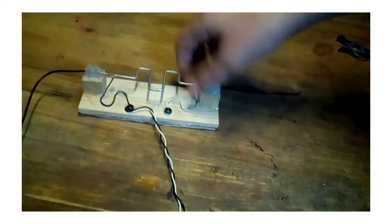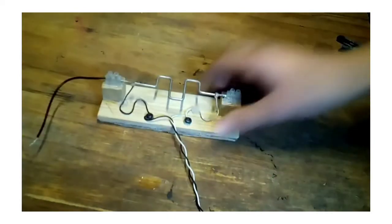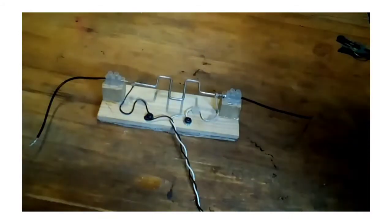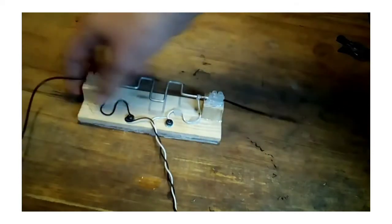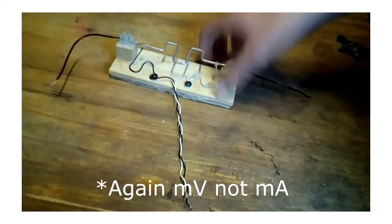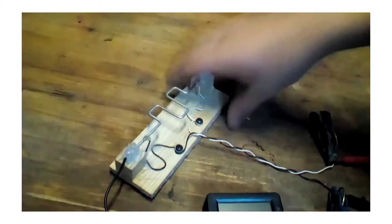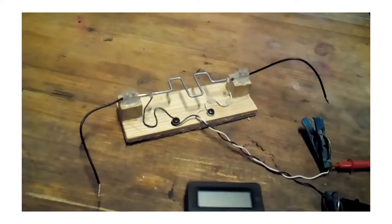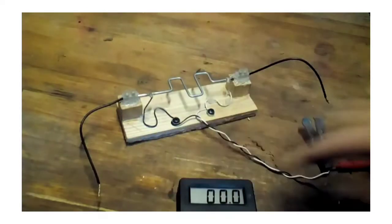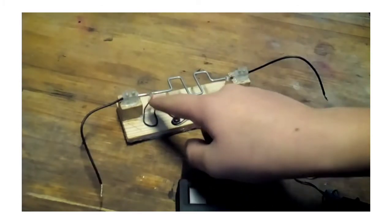and I glued these blocks of wood to this, and there I put connectors like this, and there are just wires, and you connect those to a multimeter, set on millivolts, and you're ready to go. It measures up to about maybe 100 amps. So there I connected my multimeter, set to millivolts, and the wires are connected to there and there. It measures the voltage drop.